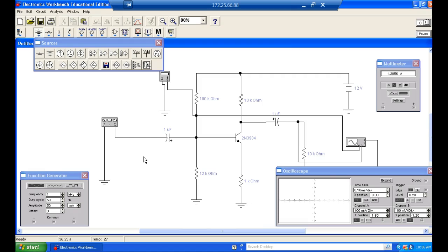They'll get a power amplifier, and then they'll run it off the preamp. Power amplifiers run different. You can set them up for high impedance inputs or low impedance inputs. The low impedance inputs, normally you hook that to the output of your radio in your car, because you're getting a lot of voltage out there. If you hook up on a high impedance input, that means you're probably running your power amplifier off your preamp. You understand what I'm saying?